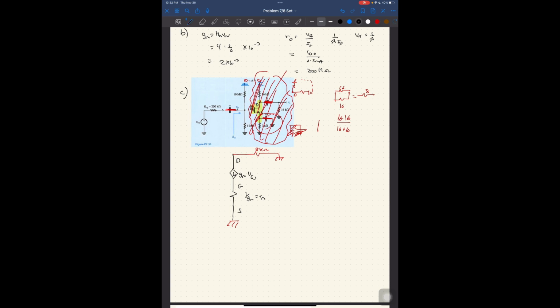And I'm now doing the second half of the circuit. I'm looking here. The gate is connected to a 10 mega ohm resistor connected to ground, and another 5 mega ohm resistor, connected also to ground, such that they're both in parallel, and 10 times 5 over 10 plus 5 should give me 10 over 3 mega ohms. Why? Because math. So this resistor is nothing but 10 over 3 mega ohms.